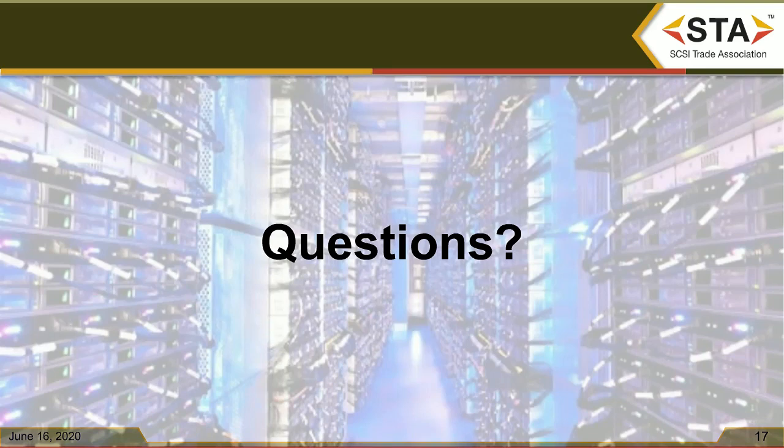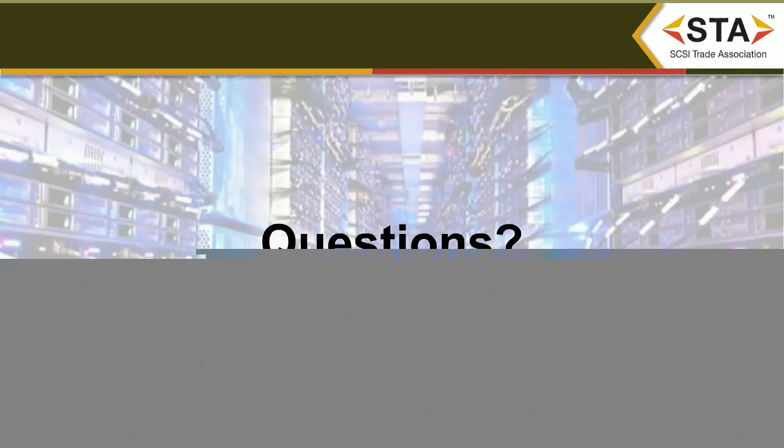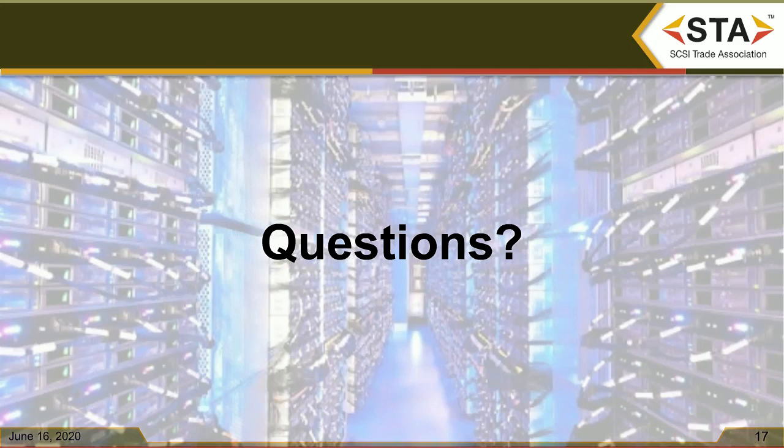Next one, Tim. In large Gen 2 or Gen 3 domains, I'm assuming SAS domains, the end devices can suffer with response time issues due to retiming delays introduced by the expanders in the past. Is Gen 4 looking at ways to reduce these delays? Yeah, that's a great question about fairness enhancements. So this observation is that as you add an expander, and if you daisy chain to another expander, another one, what happens is when a transaction's finished, the host says, I've finished this transaction.